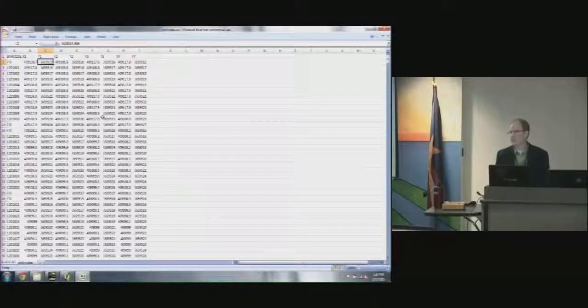If you know the coordinate for some reference point in your field, and you know the width of the plots that you want and the length of the plots and the alleyways between, you can go through the mathematical exercise of making the calculations for corner coordinates, knowing that from the UTM reference point, the meters number increases as you move east and increases as you move north.